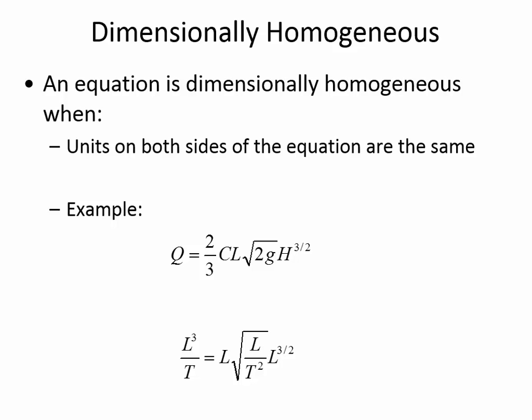And then on the right side, we're interested to know, is that the same? And so the length of the weir, how wide the obstruction is in the flow, would have units of meters, which is length. Underneath the square root here, g is, of course, 9.81 meters per second squared, and so the meters is units of length, time from the seconds is t squared, and then length to the 3 halves, and so that's 1.5, and so we have 1.5 plus another half plus another 1 gets us to 3 for the length, and then since t was squared but is in the square root, then it ends up just being units of time.